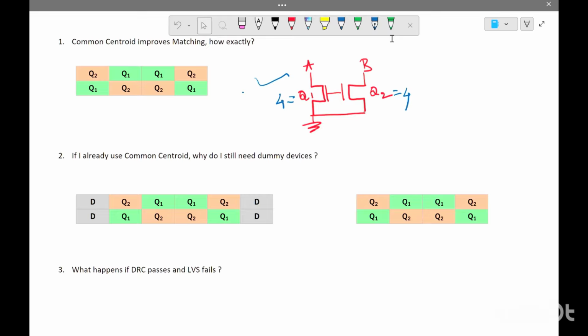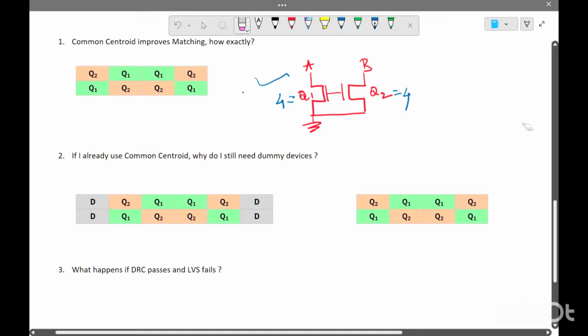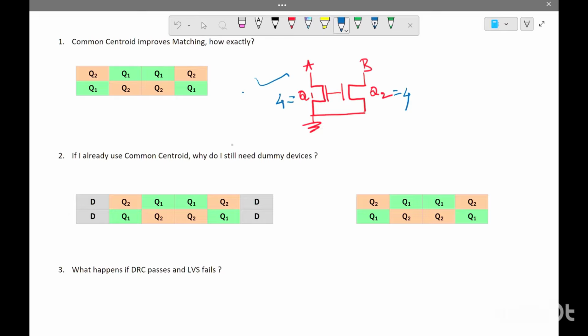Gradient effects can be like etching and all that process variation. So the dummy devices, whatever you place at the end, will absorb those process and etching variations. For example, let's take this as the only layout that we have placed. If I get the silicon of this particular layout, the edges may go something of this sort, because of your process or etching problem. Every machine will have some tolerance, and because of that machine tolerance or the process environments, all that matters during the manufacturing stages.